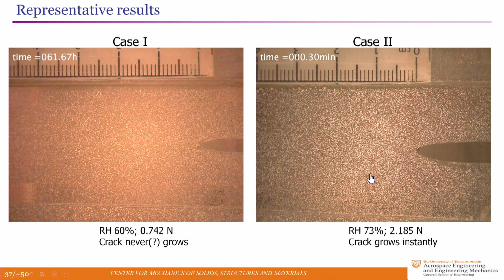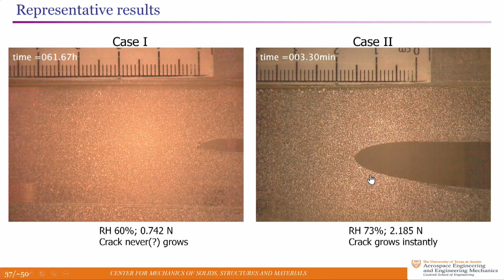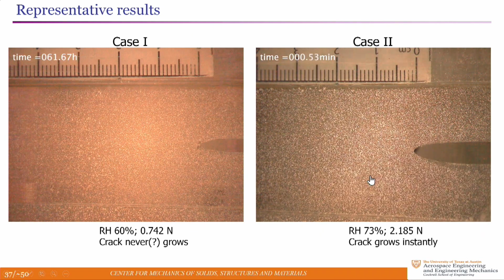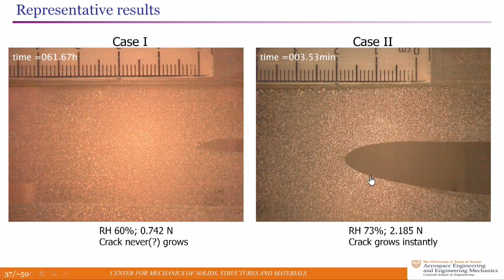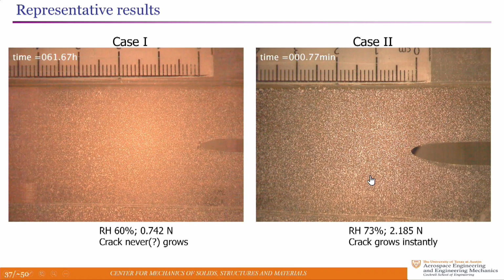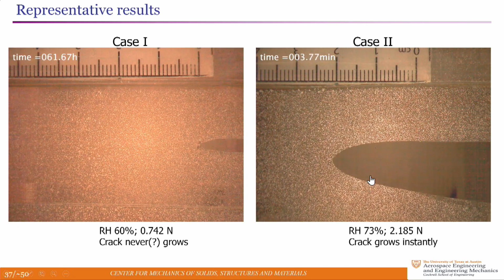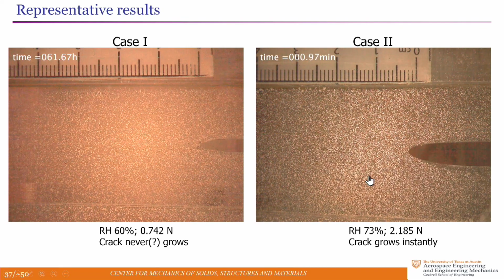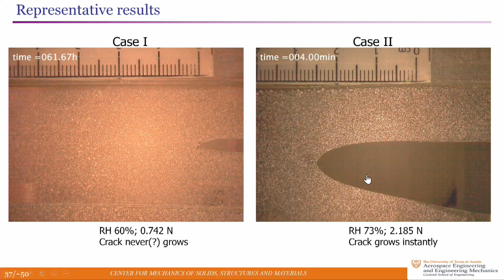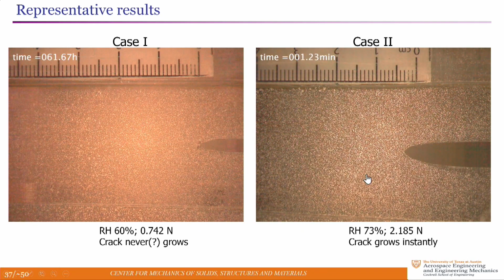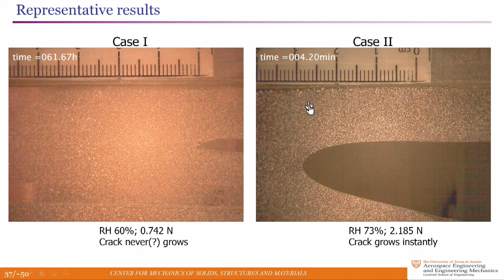And what happens here is as soon as the load is applied, it reaches critical state and the crack starts to grow. Now in this specimen, because of a dead load, as the crack increases, the work done by the weight increases, the crack continues to be loaded, and so it runs away. Now these are all accelerated. They're moving at microns per second, microns per minute, right? They're time accelerated. So this totally took about 5 minutes. So these are two ends of it.